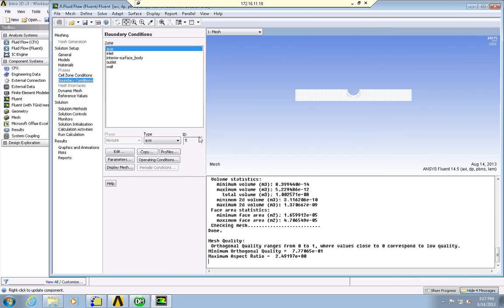One important thing is the axis must lie on the x-axis, or at y equals 0. This is very important. If we had designed our geometry where the bottom edge here was not at y equals 0, the whole thing would fail. Okay, we did that properly in the geometry, but I didn't actually mention that part.